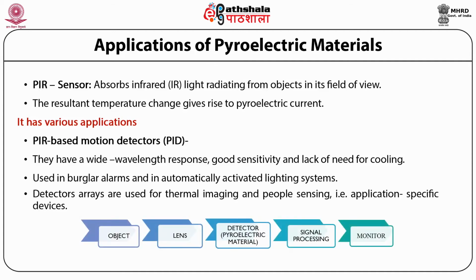Detector arrays: the market for infrared imaging is expanding. These can interpret scenes from comparatively low resolution, non-invasive images sensitive to motion, and provide cost-effective solutions. They are being used in the counting of people, and if provided with artificial intelligence, they can serve for security and healthcare. They have the potential to be used in very large volume applications in environments where video systems are limited. The integration of ferroelectric thin films directly onto the silicon substrate has reduced array fabrication cost and increased performance through reduced thermal mass and improved thermal isolation.